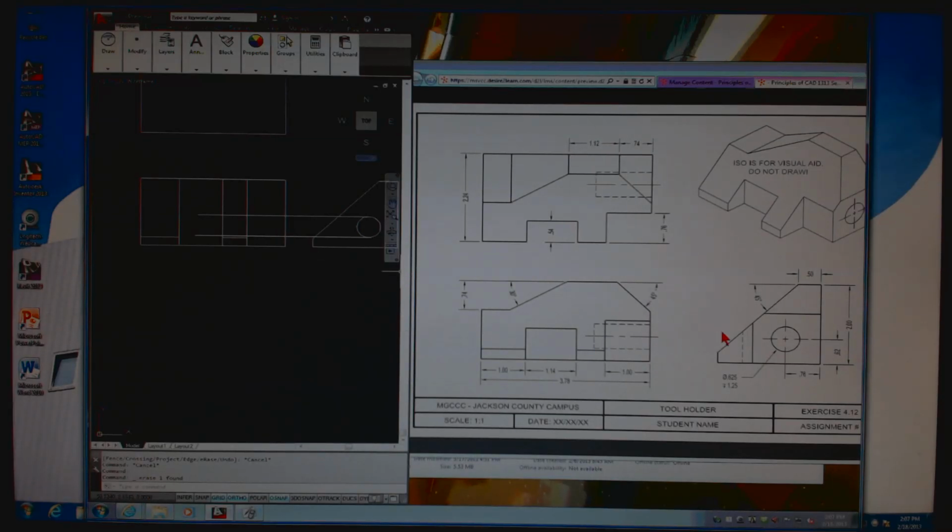There's something else that I know, I was hoping somebody would catch. What's this tell me? It tells me the depth of that circle. It tells me it goes in 1.25 deep. So I can actually copy this in 1.25, and now I can trim that.